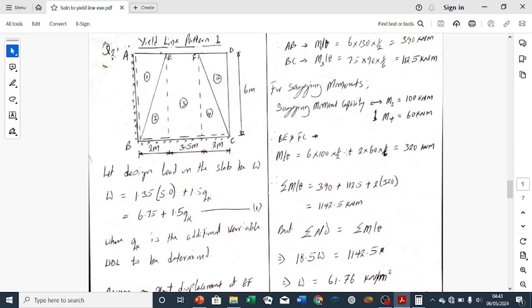We now go to the horizontal component, plus. The horizontal component is this place here, where in M L theta the length L is 2. Now the M: when calculating this horizontal component, it is the vertical reinforcement that will resist that yield line, and the capacity of the vertical reinforcement is 60. So that is why we have 60 here. And here, this is the place of maximum displacement, and that distance is 6 meters.